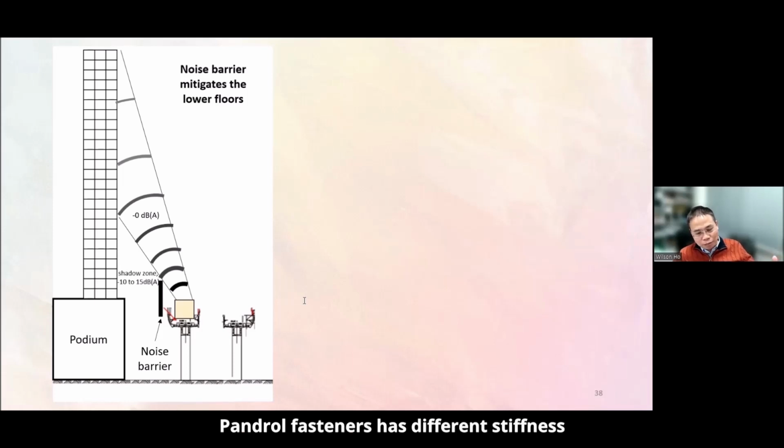Pandrol has different stiffness fasteners, very soft, as soft as 5 or 6 kilonewton per millimeter, or very stiff, 100 kilonewton per millimeter.